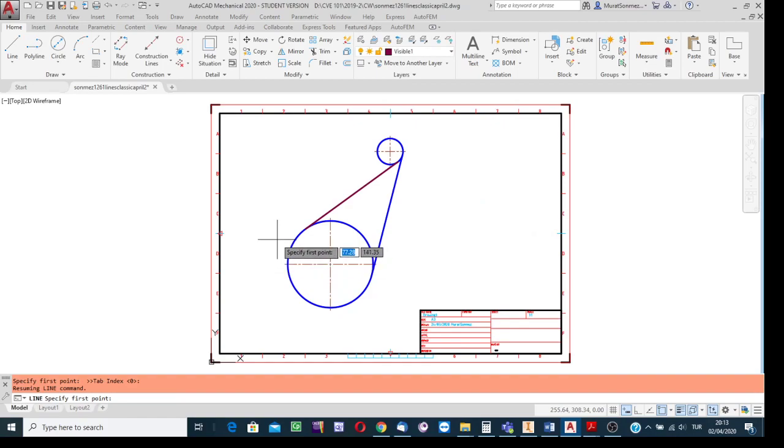Then clear all and enable the software for tangent points only, and then say OK. Then bring the cursor to the vicinity of the available circle to which the line must be tangent at this quadrant. Indicate the circle at that quadrant after seeing the tangency symbol. Okay, the line simulation has started, but you see the case is strange. There is no arc simulation. There are no boxes to write the length, etc. The second trick: it is important to say that you are going to write the length value and input the angle relative to the tangent point.